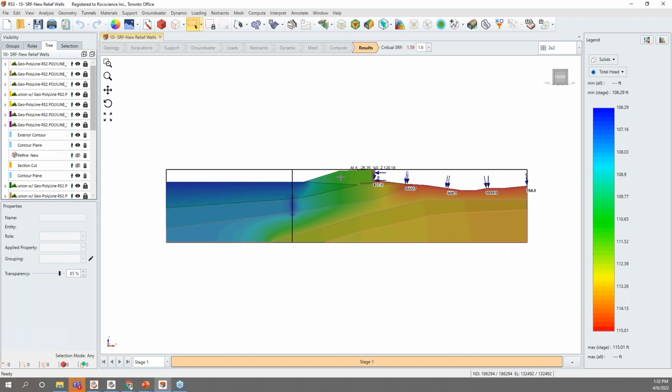So this is our levee, and this is our retaining wall, and we have ponded water behind. You can do the 2D analysis, but the thing is we have relief wells here, and when you define relief wells in 2D, the assumption is that the length of the relief wells is infinity. In the next webinar, where we compare 2D and 3D, I'll talk about differences between 2D and 3D a lot, but I am justifying the reason that we use the 3D analysis for this one.